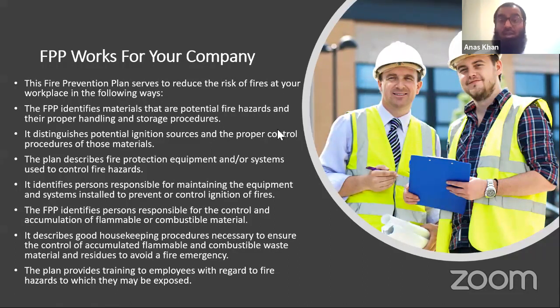Nowadays, it's a mandatory requirement from the fire company. We have fire resistant paint, fire resistant walls, and insulation. Many hotels now avoid having one duct for all rooms, because of the accident in UAE where the fire was small, but due to the smoke, many of the interconnected HVAC lines carried smoke into the rooms, and many casualties happened. So they avoid having too many rooms on one single pipe. They again make compartmentalization, a few rooms with one line, so in case of any fire, not everyone is affected.